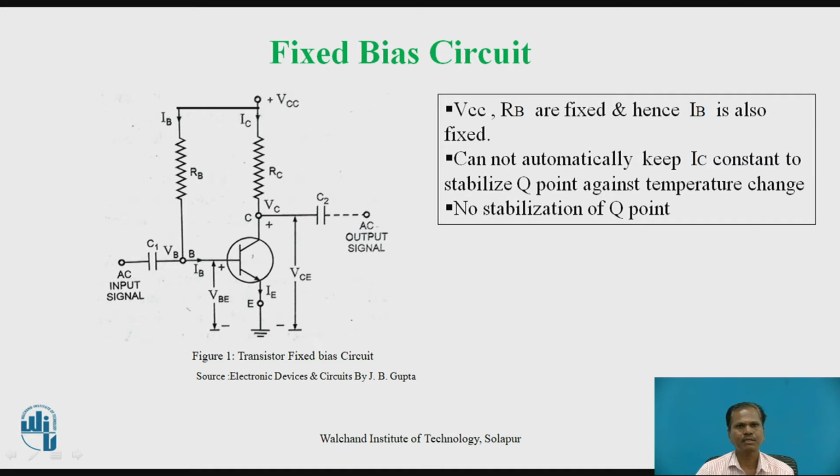So, let us go for the first type of transistor biasing circuit. Now, this figure shows the circuit diagram for common emitter transistor amplifier in which fixed biasing circuit is used for biasing the transistor. In fixed biasing circuit, as shown in this circuit diagram, the base biasing voltage is obtained from VCC and using fixed resistor RB, base resistor RB. So, circuit is designed around base and collector circuit. Usually a transistor like an NPN transistor is shown in this circuit diagram.